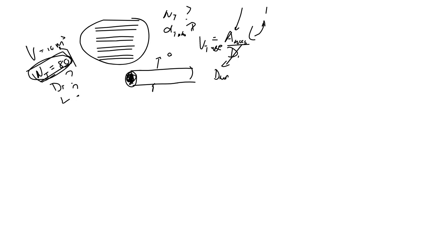So it's an interplay: I must fit this amount of catalyst in this amount of tubes, and I can change the number of tubes, the diameter of the tubes, and the length of the tubes, and one of them must be a loose variable, if you understand what I'm saying. I can't fix all three of them simultaneously, because I can't fix the diameter and the length and the number of tubes. So I'm going to leave you at that.